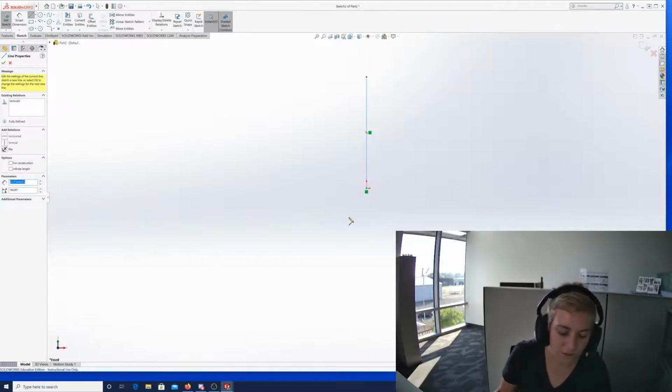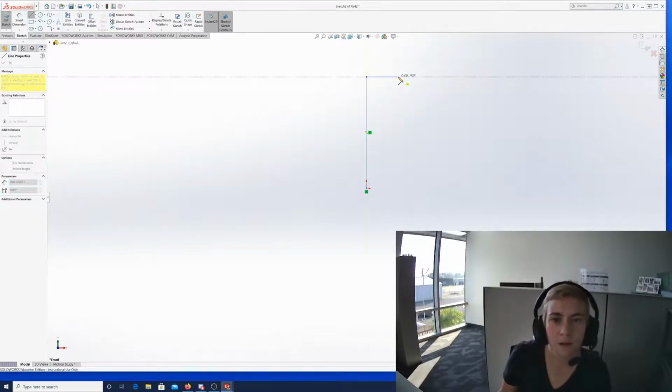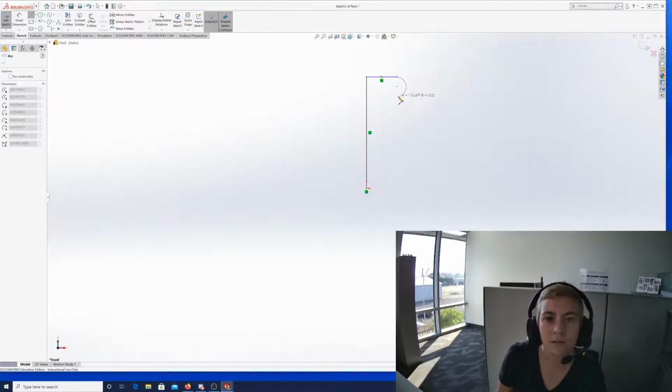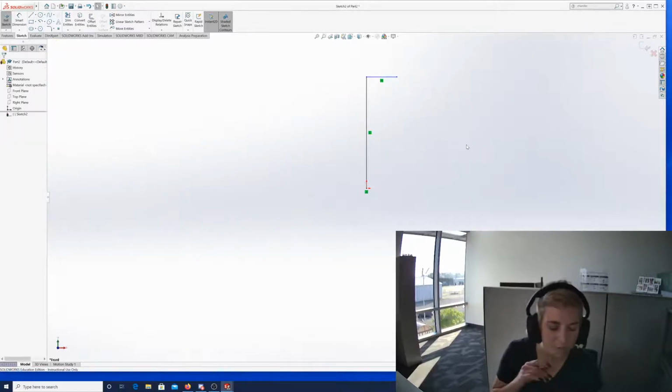That's how I did that line, but if you all just want to draw a line whichever way works for you. The other thing you can do is a single click on that point where you want to start, move the mouse over, and then do another single click to end the line. And then it's going to let you keep going if you do it that way. It's going to give you this option to continue with another line or an arc. If you hover back over it, you can just hit escape to get out of that.